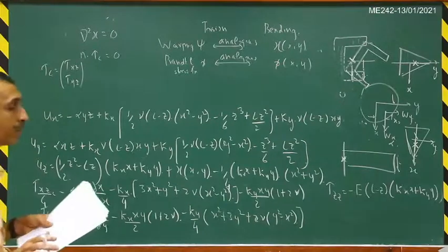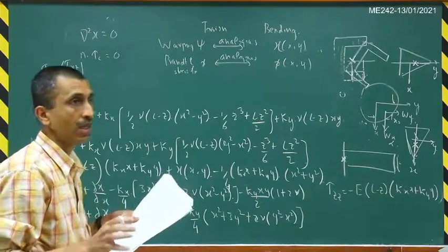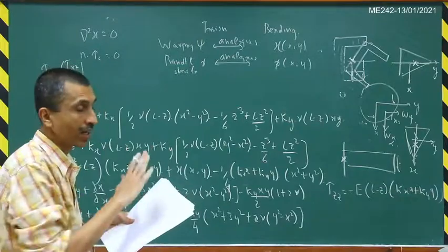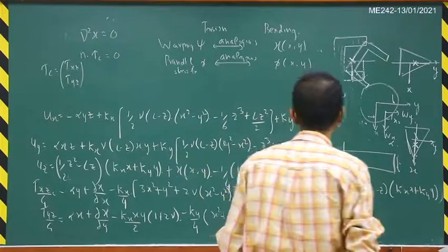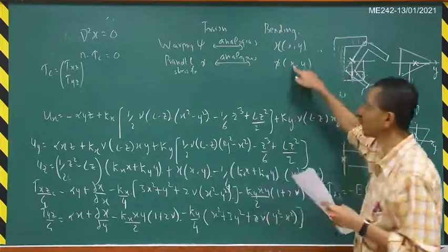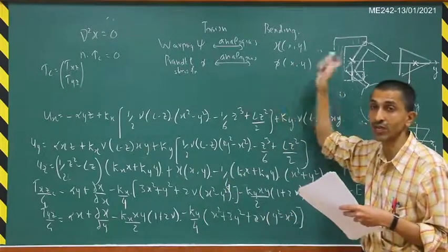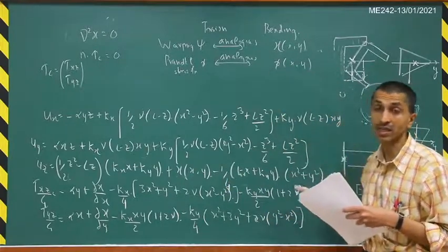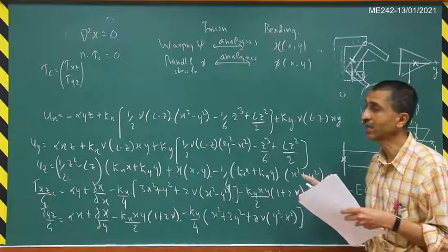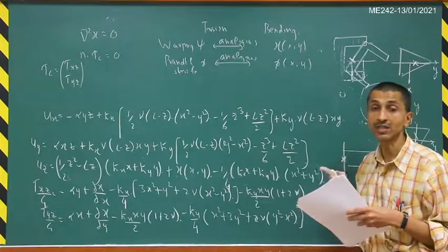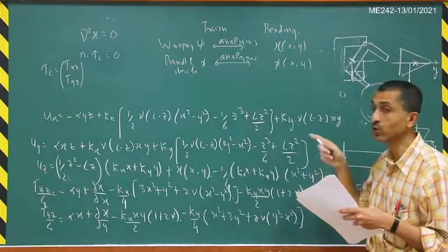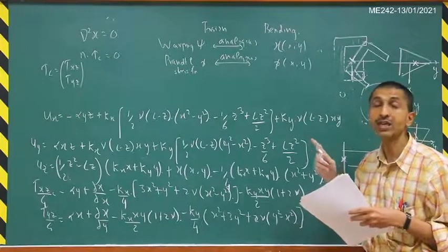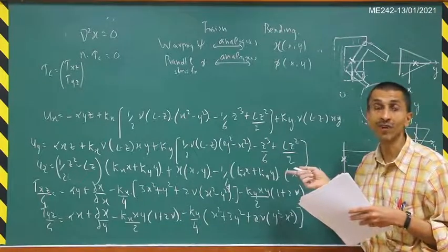So let me summarize now the situation for this bending by terminal load. Either you can formulate the problem in terms of this function phi, so that equation del square phi and so on, but there is a catch there: only when those two conditions are satisfied, which involve dy by ds and dx by ds, will the boundary condition get simplified to phi equal to 0.